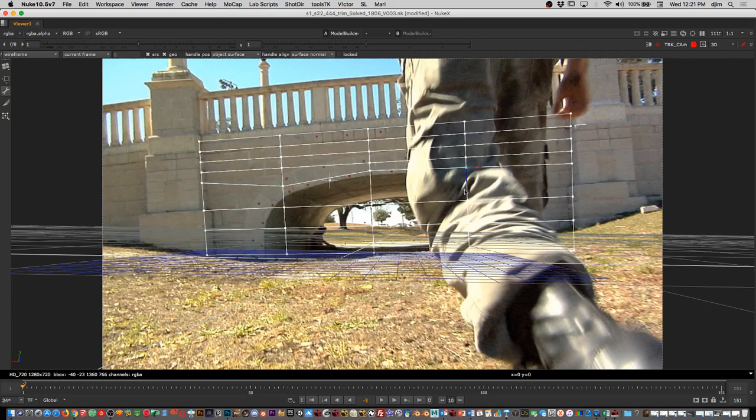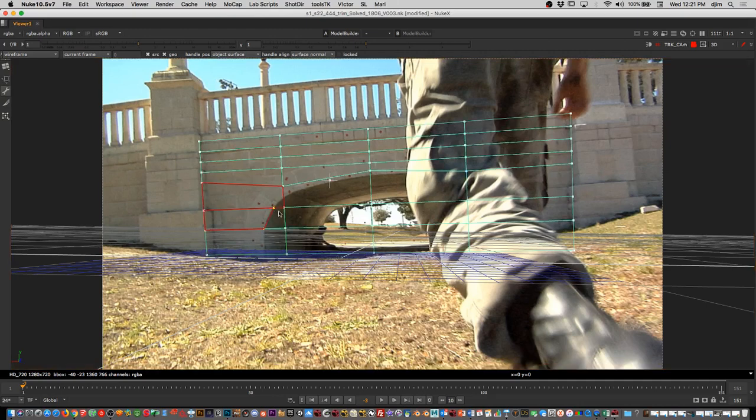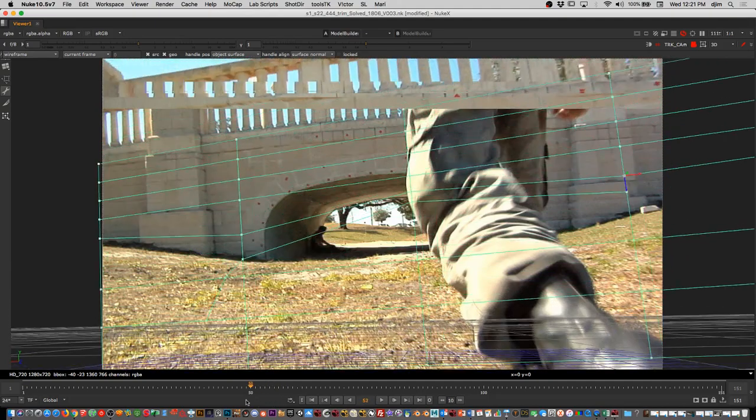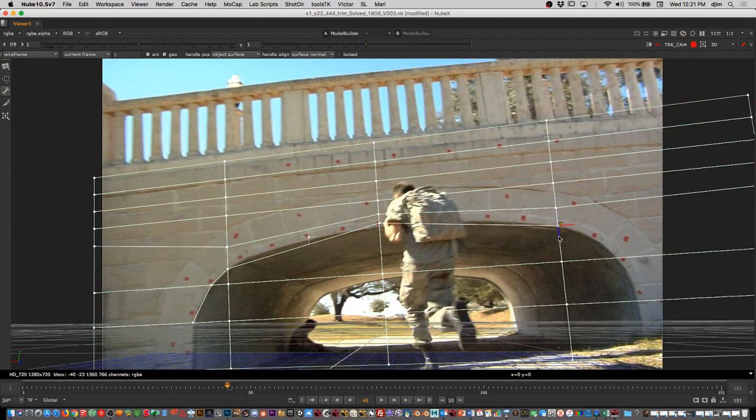So let's say you decide, yeah, you don't want to do that much work. So there's a tool here that you could actually use called the carving tool. So if we click on the carve tool, we could actually click on what we see, and we could carve away our shape, right? So on that side, I don't see it, so I'm going to hit enter very quick to commit it. I'm going to go to a plane where I could actually see it, and then let's move this guy down right there, and let's continue the carving.